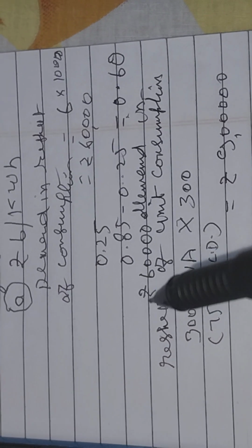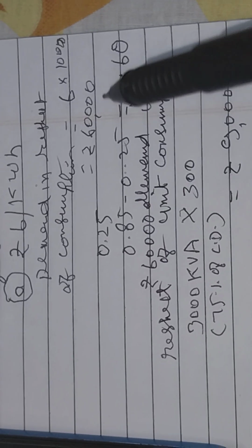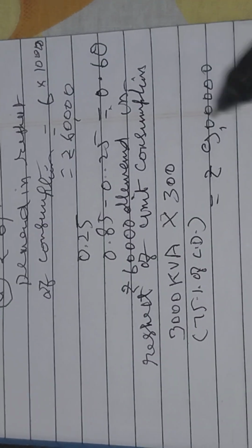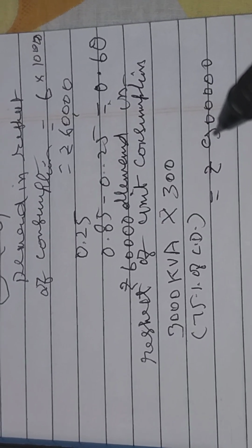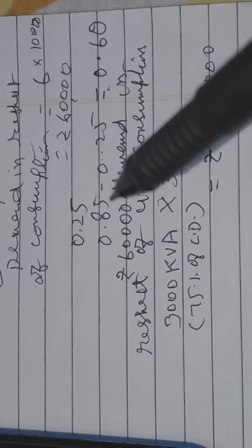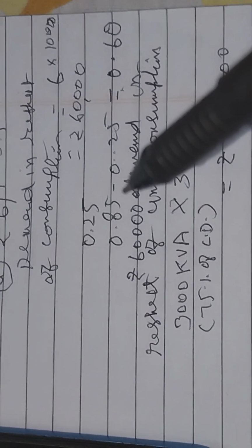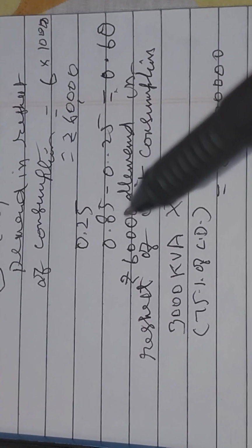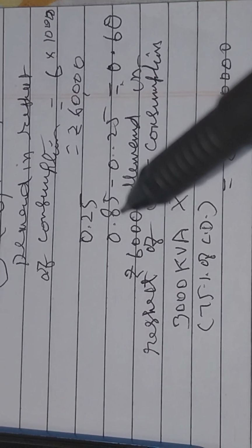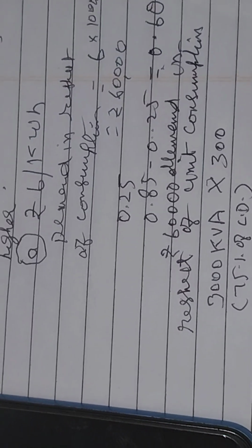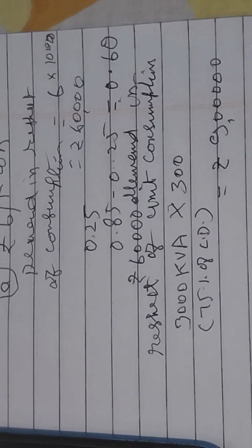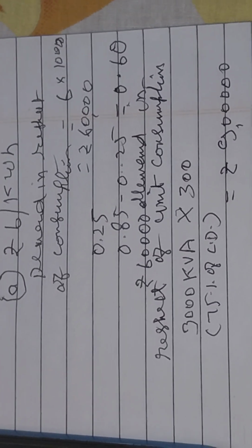So what we see here, for poor performance and inefficient use of the system, the consumer is charged only 60,000 in respect of consumption, but rupees 9 lakh as power factor penalty. On the contrary, if they maintain power factor above 0.85, up to 0.9 there is no incentive, but from 0.9 to 0.95 they get a rebate incentive at the rate of 1% for every increase in power factor above 0.9. So this is the way to tackle the power factor, the worst enemy of the power system.